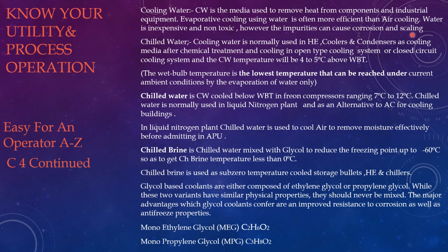It can be treated in the cooling tower based on the selection of cooling tower type, whether it is corrosion type or scaling type. You have to select your cooling tower, then you have to use corrosion inhibitor and descaling agent to treat the water. You might have seen cooling tower details in the previous slides. If you want to know more, watch my previous videos about cooling water and cooling tower system.